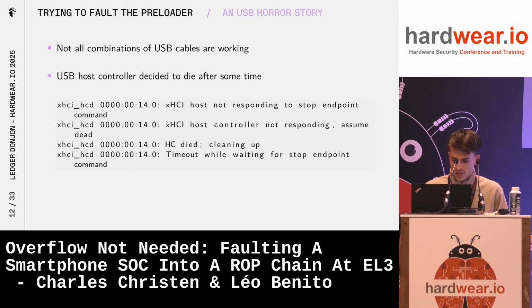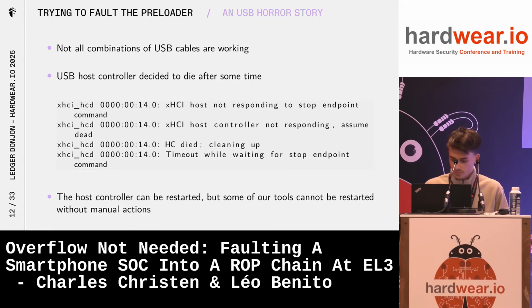The issue here is that the USB host controller decided to die. So what the host controller sees when we are resetting the device is a USB device that is disconnecting, and then a new USB device that is connecting. And after a huge number of USB connection and disconnection, the host controller dies for some reason. We managed to restart it.